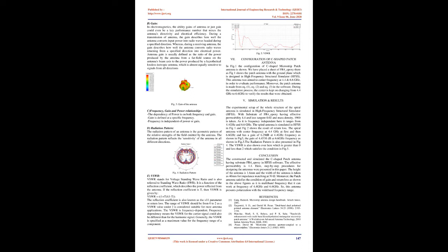An antenna's return loss is a figure that indicates the proportion of radio waves arriving at the antenna input that is rejected as a ratio against those that are accepted. It's laid out in decibels, dB, relative to a short circuit, 100% rejection. Consider the antenna being used in transmit mode.